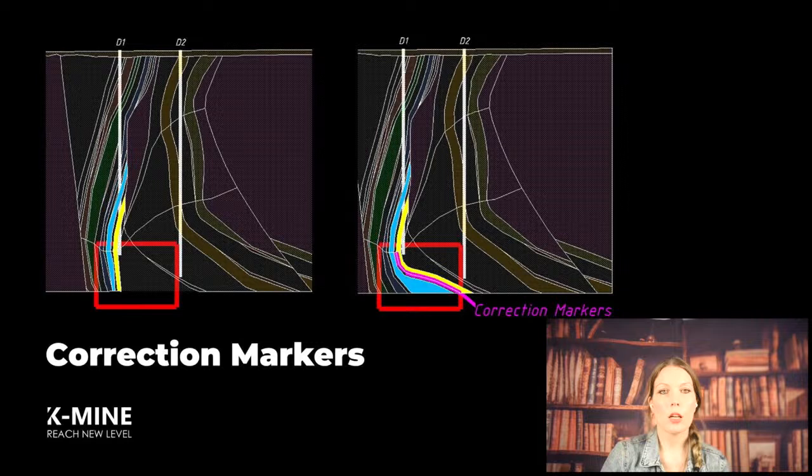To use this, first create a wireframe surface from the bed floor in the areas where you want to adjust the contact positions and, as a result, the bed thickness. The algorithm will incorporate the triangulation points from your surface when building the block model.